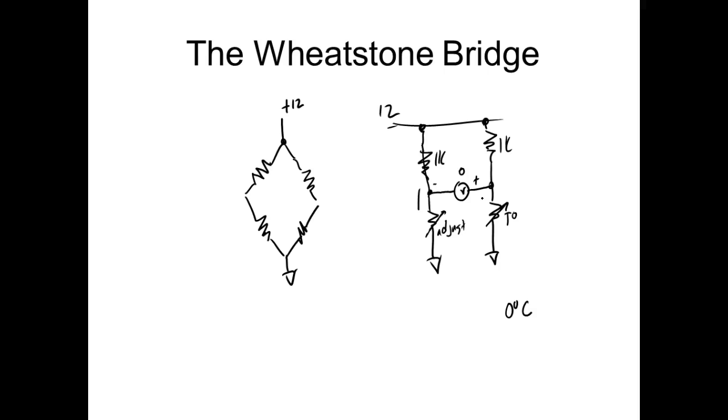We do have another one called a 4 milliamp to 20 milliamp, and it's called a current loop. So the advantage of the current loop is that we're developing a current. The problem we have with voltages is that voltages are susceptible to electromagnetic interference, which we call EMI, right?